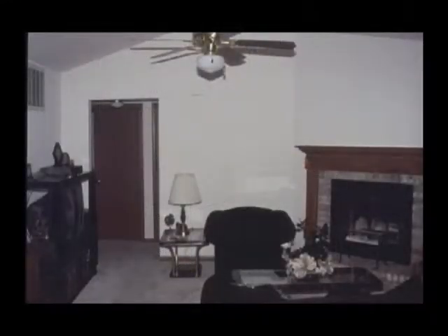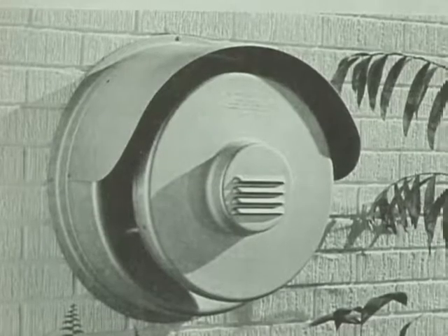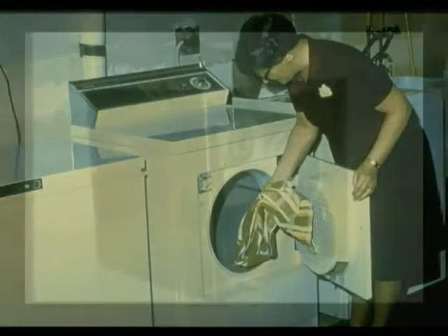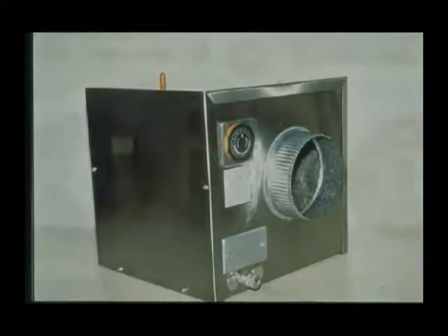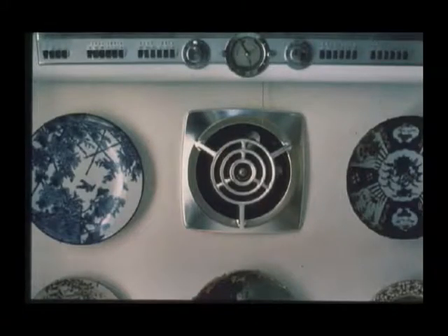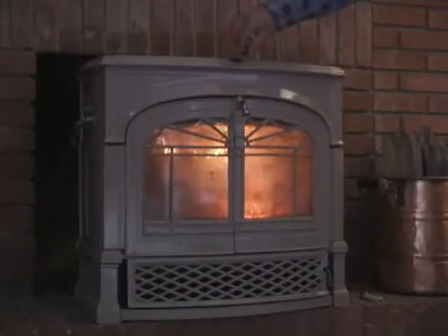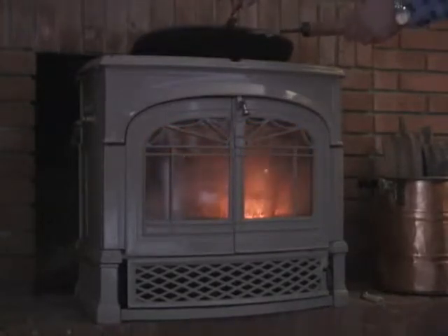Another significant cause of negative pressure is other devices that draw air from the house or the combustion appliance zone. The most powerful are fireplaces and downflow kitchen barbecue exhaust fans or other commercial-grade exhaust fans. Next are clothes dryers and whole house exhaust fans. Smaller exhaust fans, such as in kitchens and bathrooms, can contribute to the problem. Any other vented appliances that use air from that space can also contribute to negative pressure problems. And even an exhaust fan outside the living area, such as a powered attic ventilator, can suck air from the house or CAZ.